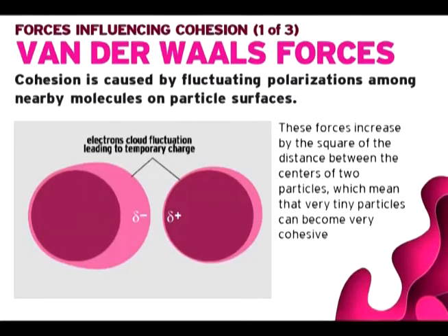The weakest attractive forces are usually van der Waals forces. Fluctuating polarizations among nearby molecules and particle surfaces trigger these forces. Van der Waals forces increase proportionally to the square of the distance between two particle centers, meaning that even very small particles may become extremely cohesive. Van der Waals forces are the reason why granular sugar can be very free-flowing, but finely ground confectioner's sugar can